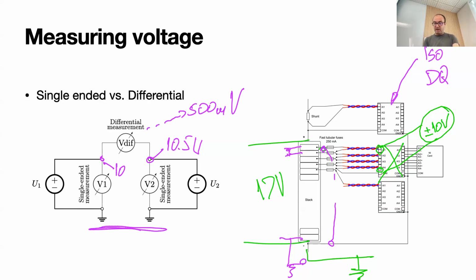And one peculiarity in this scenario is that the shunt is connected to its own data acquisition, because we don't know where the shunt will be connected. If the shunt was connected above the plus, then the shunt will always be higher than the stack. If the shunt was connected to the minus part, then we could have connected it to the last data acquisition module.